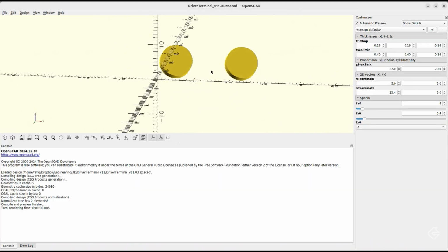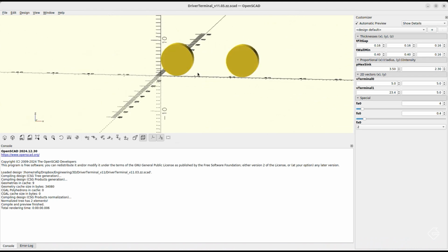So basically, the front or the leading edge of our part is going to be slightly thicker than the side or the flank edges. And what we want to do with those parameters is extend these circular solids so they cover the leading and the front edge. But of course, we're not simply going to scale the circle. I'm going to add some interest to that shape.